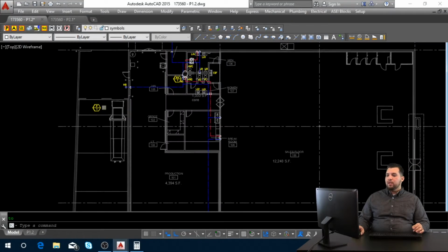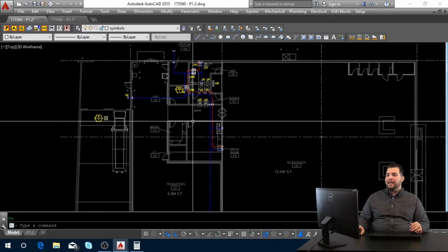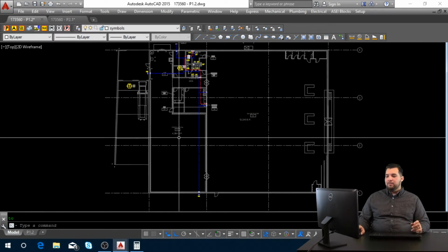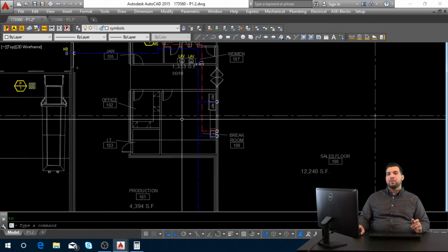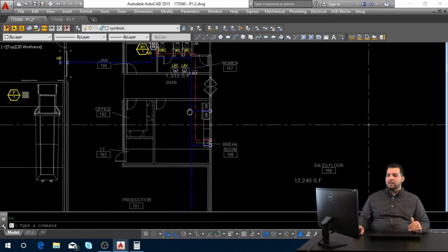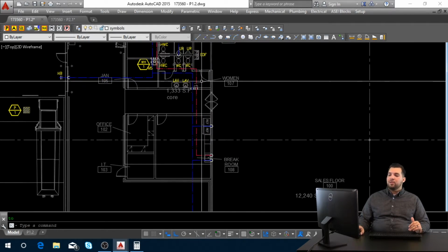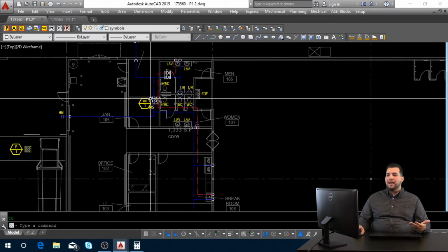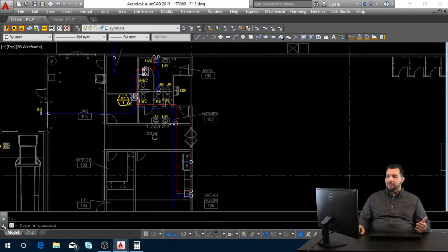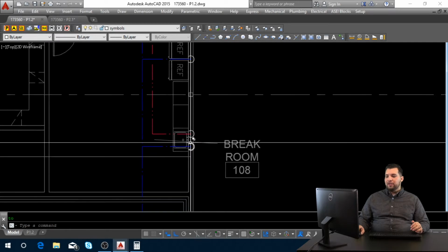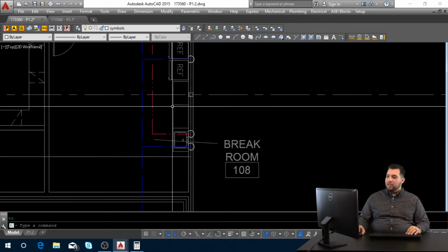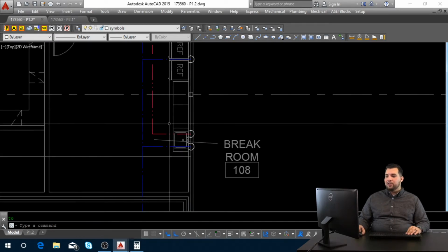When you want to do your water line sizing, you want to work your way back from the furthest fixture. It's a lot easier when we start with our hot water line, and we do that with our main lines, and then we're going to come back and do our individual lines later. What we need to do is figure out how many fixture units are in each fixture.